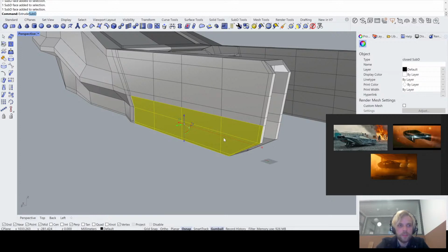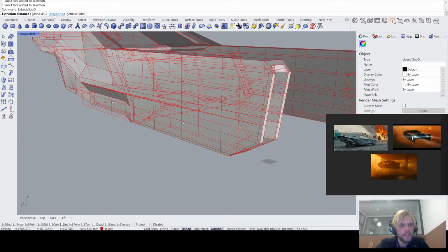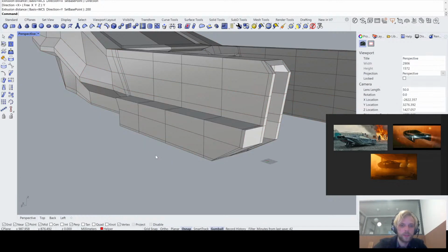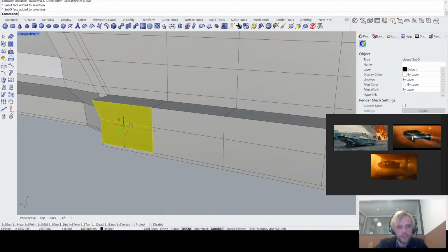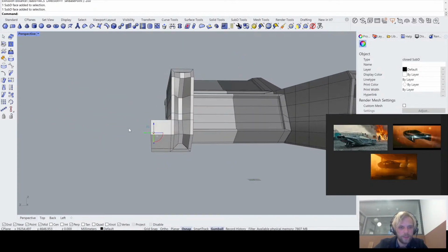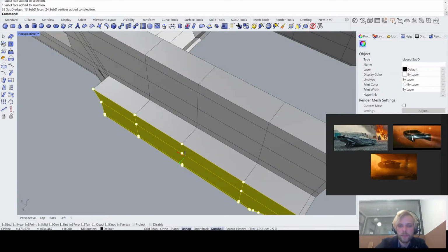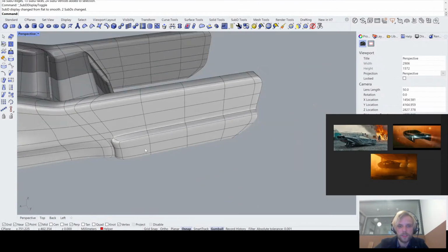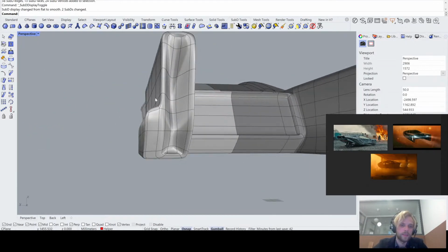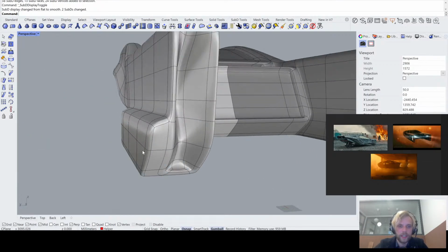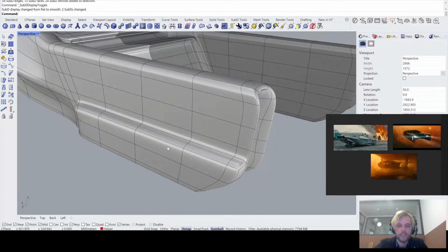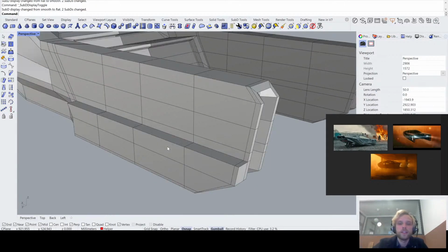Okay, extrude SubD. This time not in X but in Y direction, and in positive Y we will give it like 30 centimeters. No, less than 30, 20 centimeters, 200 millimeters. Oh, that was even too much. Is there a fast way for me to just do this? Yeah, cool. That selection works. Minus 100, only 10 centimeters. Bam. Yeah, that's much better. This is something I can work with actually. So that's good.